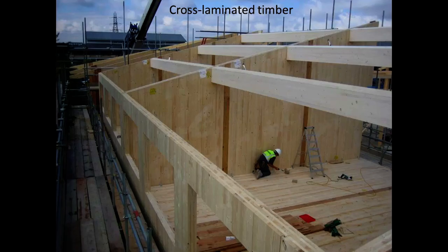There are other kinds of, shall we say, monolithic load-bearing walls. Normally, what we call laminates. Now, laminates are when we layer materials together, where we layer thin panels of materials together, and that layering of materials, that build up, if you like, begins to give strength to the material. Some of you might know what a piece of plywood is. Think of a simple plywood sheet. It actually is quite stiff and strong, can take load vertically onto it. It's because it's a layering of materials.